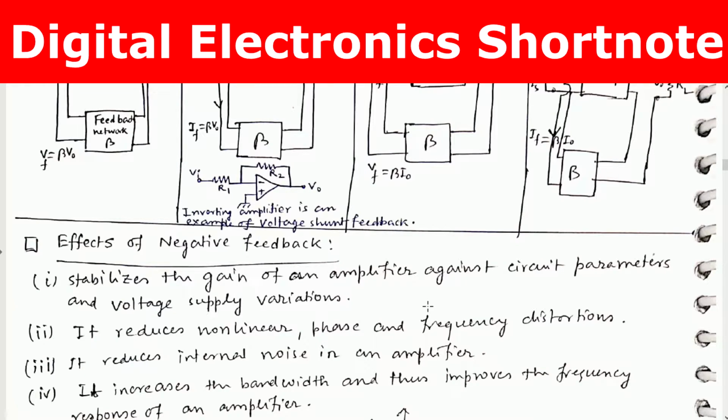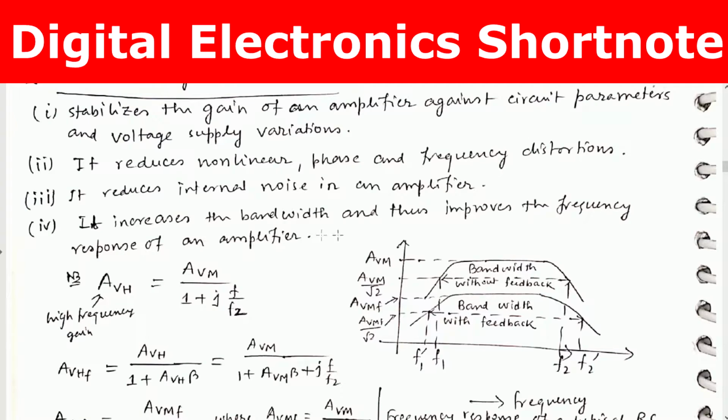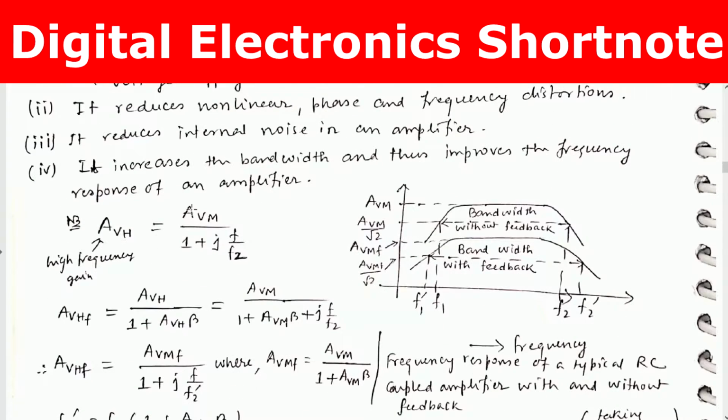Effect of negative feedback. So basically negative feedback makes the output less. So why should we use negative feedback? These are some advantages of negative feedback. Firstly, it stabilizes the gain of an amplifier against circuit parameters and voltage supply variations. It reduces nonlinear, phase and frequency distortions. It reduces internal noise in an amplifier. It increases the bandwidth and thus improves the frequency response of an amplifier.